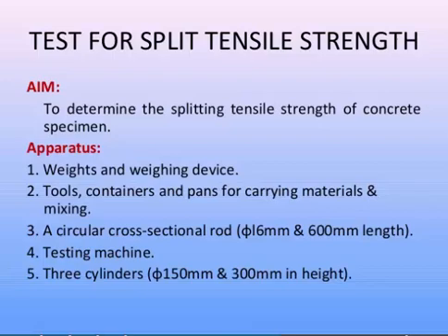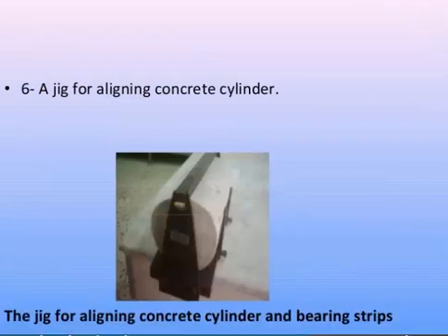It is a very important parameter that when we are going to fill the mold with concrete, either the cubical mold or the cylindrical mold for the split tensile strength test, it needs to be greased. It needs to be oiled properly from inside, so that sticking of material with the plates of the molds may be avoided. So these are the various apparatuses which are considered in this test.